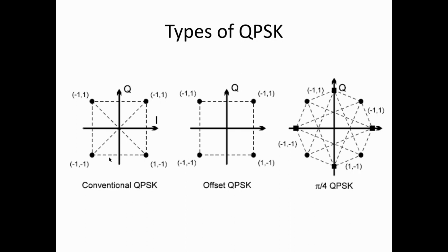So if you want to transmit two bits simultaneously, 1 to 0 and 0 to 1, obviously the QPSK will have a 180-degree phase shift. That 180-degree phase shift crosses the zeroth line. Whenever it crosses the zeroth line, it creates a non-linear effect. This non-linear effect creates a side lobe at the transmitter side. One more drawback of the conventional QPSK is that linear amplifiers could not amplify the signal to the required level at the transmitter side. So these two are the drawbacks of a conventional QPSK.